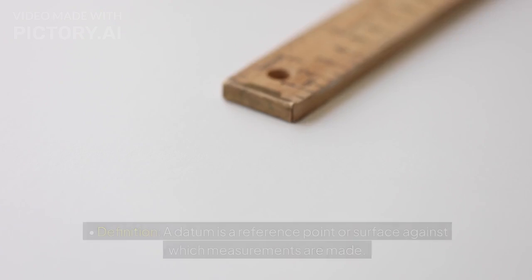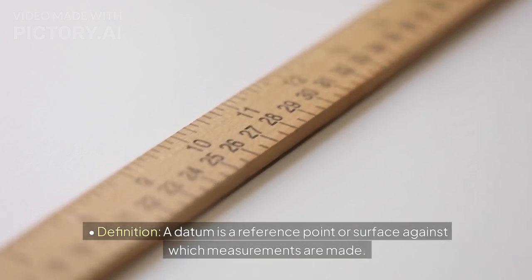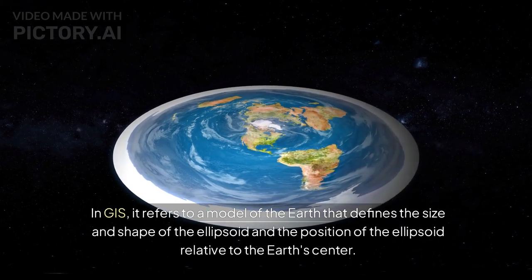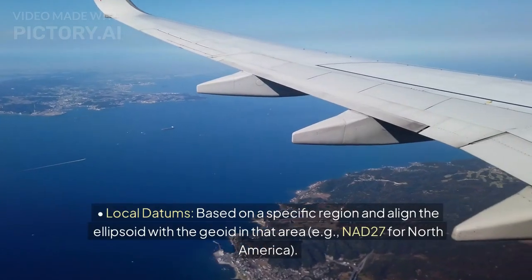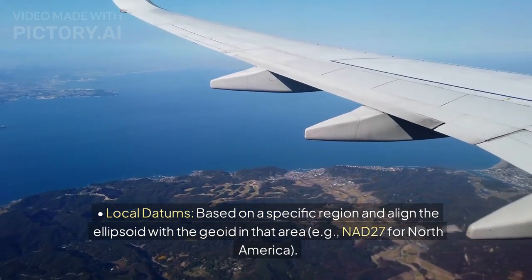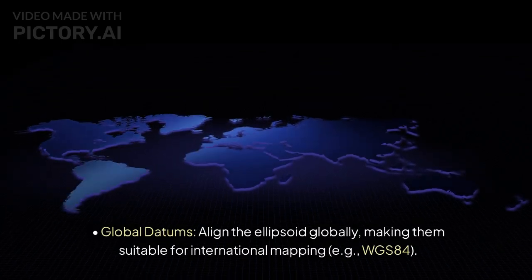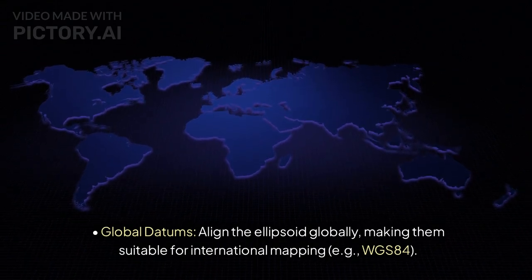2. Datum. Definition. A datum is a reference point or surface against which measurements are made. In GIS, it refers to a model of the Earth that defines the size and shape of the ellipsoid and the position of the ellipsoid relative to the Earth's center. Types of datums. Local datums are based on a specific region and align the ellipsoid with the geoid in that area, e.g., NAD27 for North America. Global datums align the ellipsoid globally, making them suitable for international mapping, e.g., WGS84.